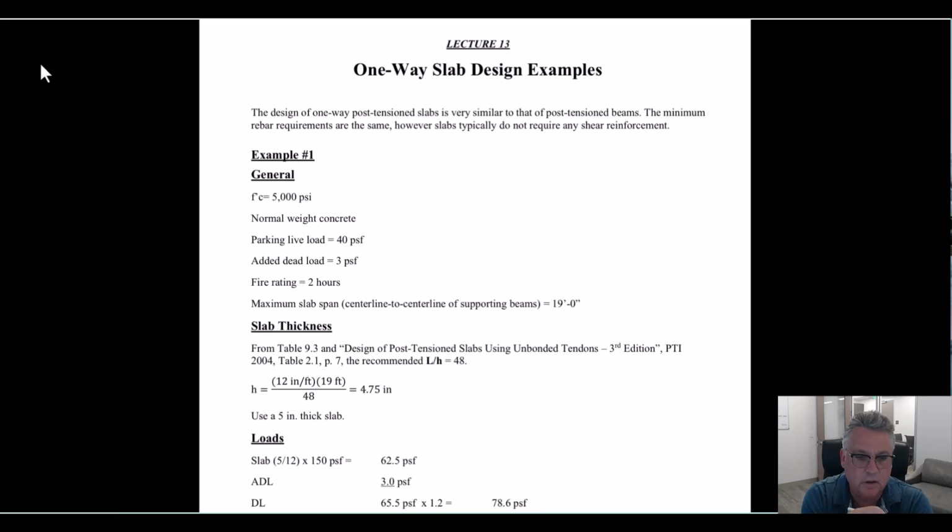In addition, we will do a quick shear check just to show you why we never do shear checks. So that messy stuff that we had to do in beams for shear, we don't really do anything for shear in slabs. The idea is that they are continuously supported at all their supports, by beams or by walls. So that continuity of support means there's not a localized high shear demand anywhere. And you'll see that in the calculations.